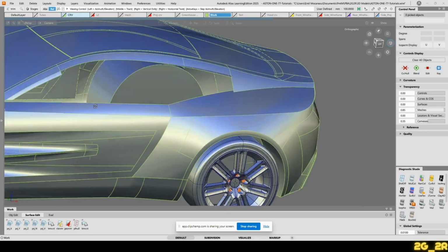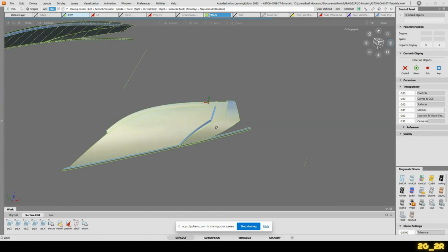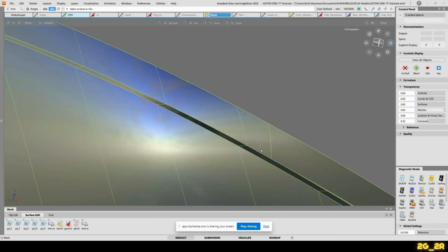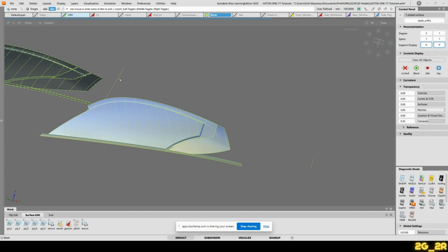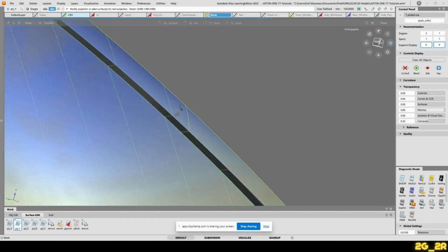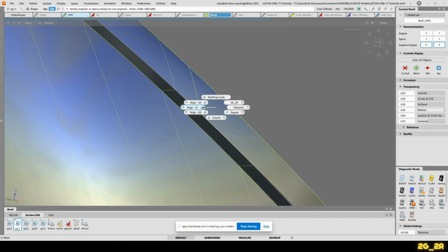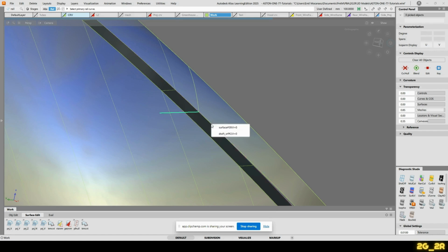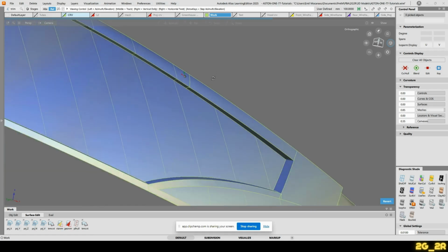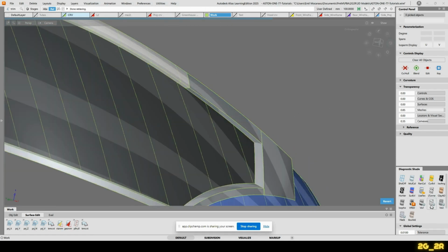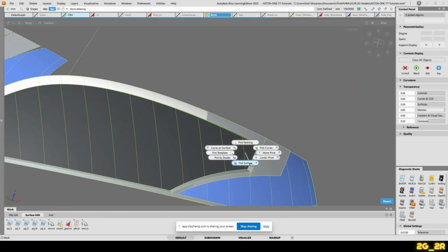Okay. Now let's add here that little finisher there. I'll do a monorail. So on this surface here, I'm gonna project the same line that we had projected on the upper surface. And what I'll do, I'll run a monorail of that curved surface on this new little surface here. And I'll trim this back. And that's done. So we've got our first rough volume.